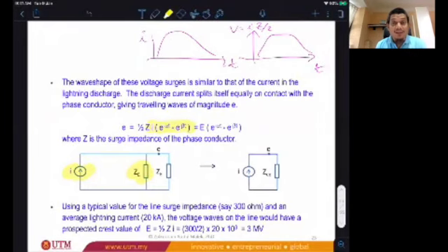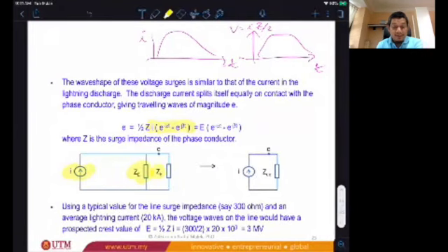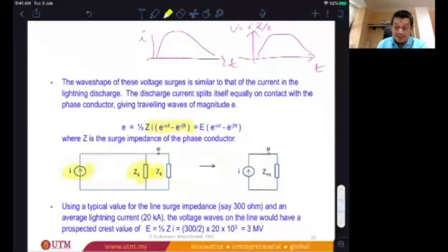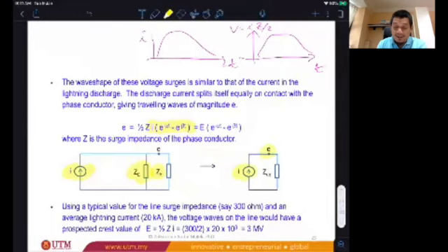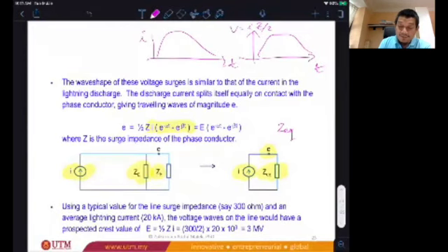Okay, E here is actually, it should be Z only, but I put earth there, doesn't matter. So you can ignore E. So Z, 2Z, and therefore the equivalent circuit is like this. I, the voltage there, and equivalent. And Z equivalent is equal to Z in parallel with the 2Z, if we ignore the E. So that's why we have Z over 2.